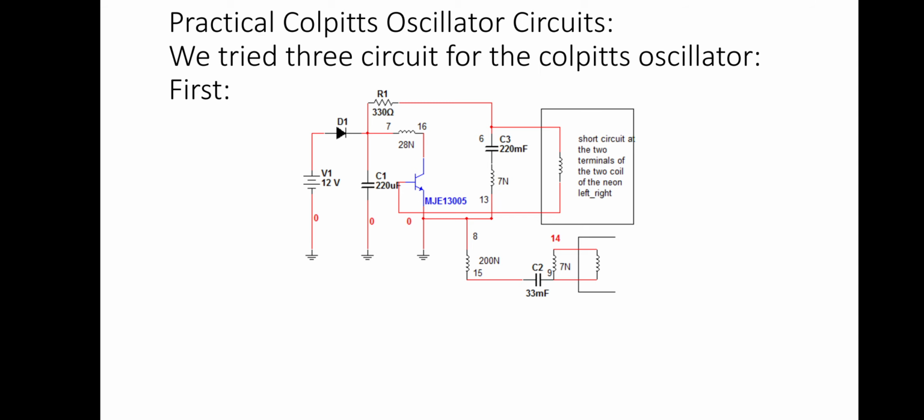The capacitor C1 has one end connected to base via CC and the other to the emitter via CE. The voltage developed across C1 provides the regenerative feedback required for the sustained oscillations.